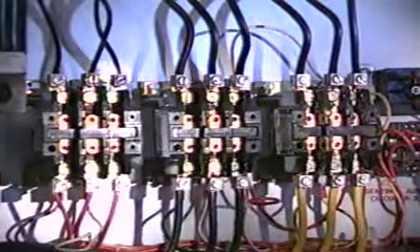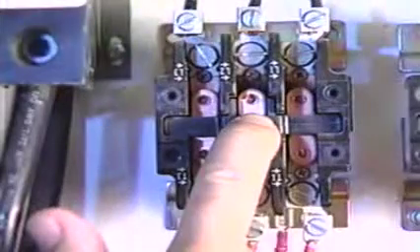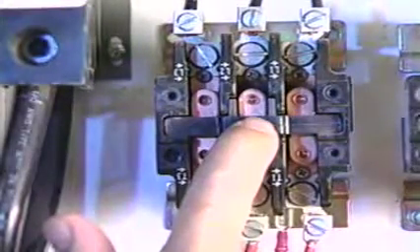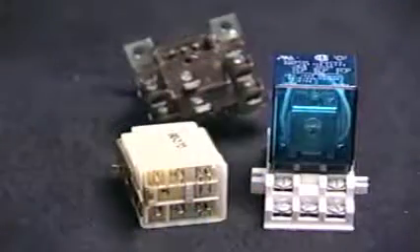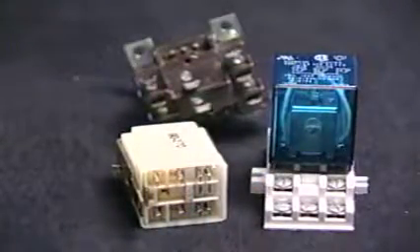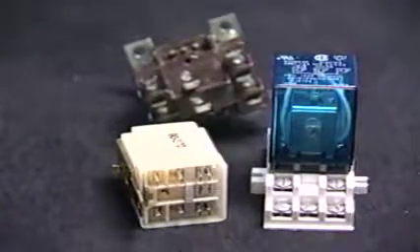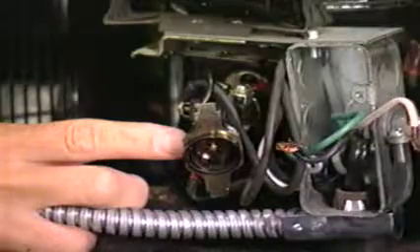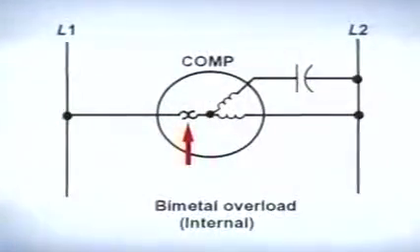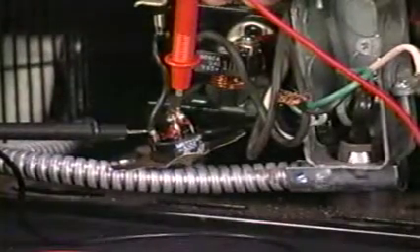Contactors cause sets of electrical contacts to open or close automatically to either energize or de-energize system loads in response to the load requirements. The contactor coil can be open, shorted, or good. Similar to contactors, relays are also used to automatically control the operation of system loads and are tested in a manner similar to that used to check contactors. Overloads protect system loads from an overcurrent or overheating condition by opening the circuit that feeds power to them. Troubleshooting overloads can be done quite easily with an ohmmeter, since these devices typically have only 2 wires.